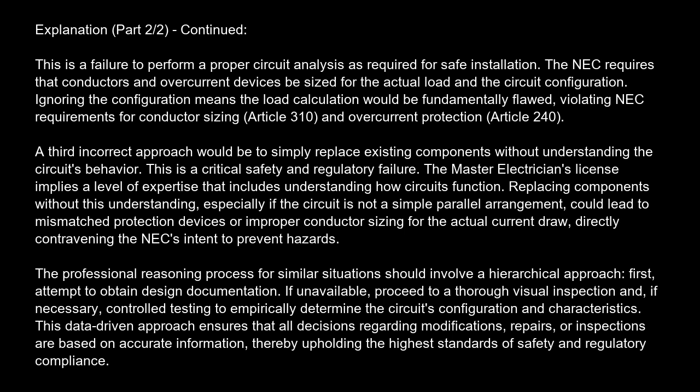The NEC requires that conductors and overcurrent devices be sized for the actual load and the circuit configuration. Ignoring the configuration means the load calculation would be fundamentally flawed, violating NEC requirements for conductor sizing, Article 310, and overcurrent protection, Article 240. A third incorrect approach would be to simply replace existing components without understanding the circuit's behavior.